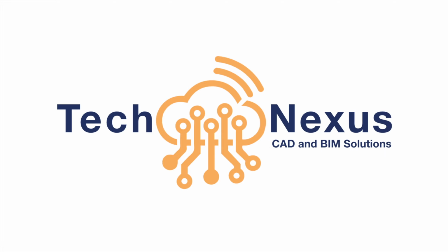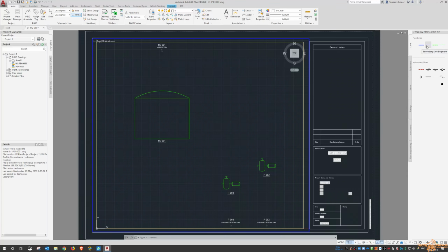Now with the P&IDs, if your line types are already set, your pipelines, then you could just pick whichever ones you need, but I'm just going to use the out-of-the-box AutoCAD P&ID lines. So we have primary, secondary, primary line segment new, secondary new, primary line existing, secondary existing, and jacketed. Now for this exercise, I think I'm just going to stick with the primary and the secondary.